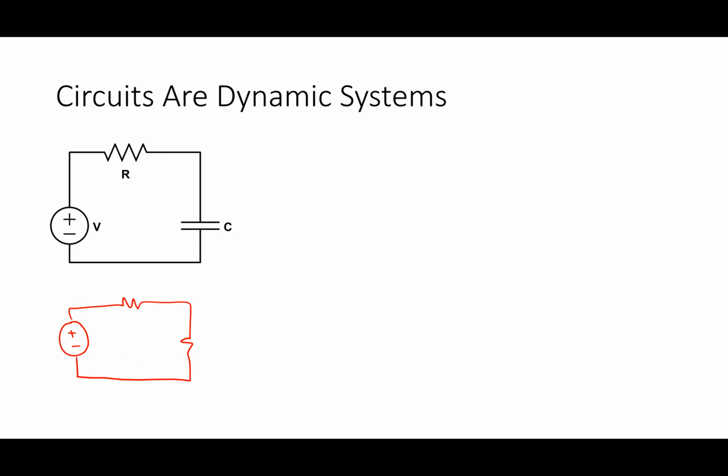Whereas when I looked at this RC circuit, we said in general, when I'm looking at something like this, I would have to do KVL around that loop and write a differential equation for it, which for this particular circuit would be V of t, whatever the input is, equal to RC times the derivative of the capacitor voltage, plus the capacitor voltage.